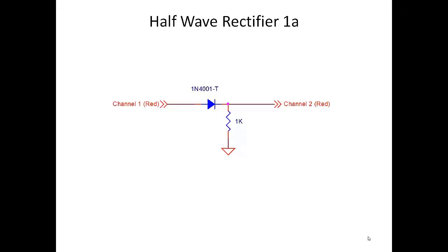For the rectifier diode, we will see what happens when the frequency becomes too high for the diode to handle. This is the first half-wave rectifier circuit. The 1N4001 is a rectifying diode, which can handle more power than a small signal diode, but not as high of a frequency. It is adequate for 50 to 60 Hz AC signals encountered in line power throughout the world.